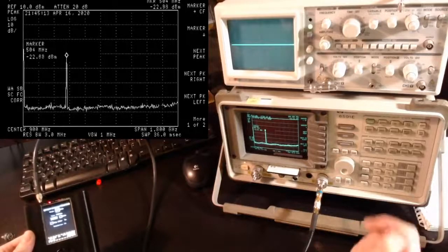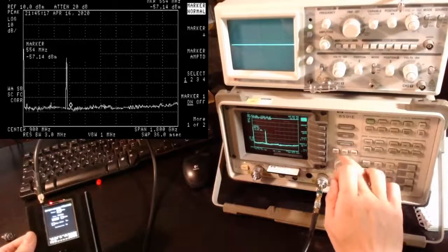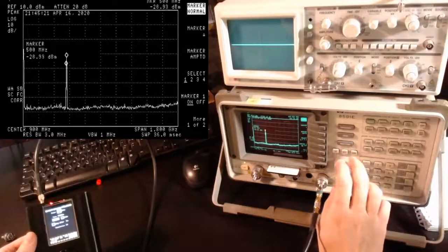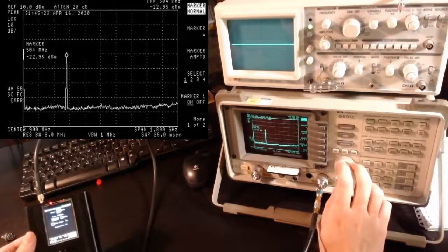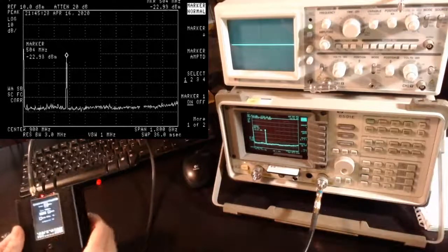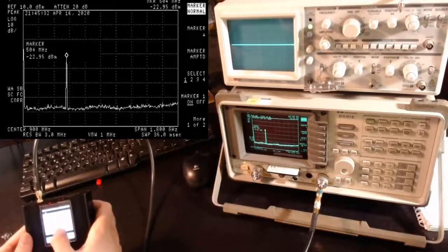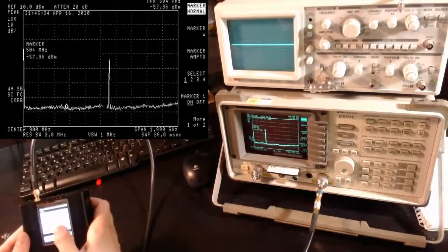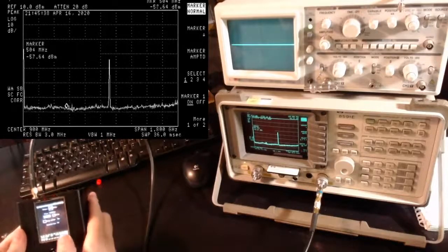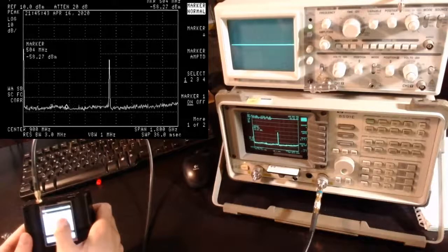And the noise floor here is, so let me just take the marker and go down, at minus 57. So it's a good 35 dB down. Okay, so the signal is pretty clean, and I think we should be happy about that. And let's see what happened at 1 gigahertz. So yeah, same thing. So it's pretty good. And let's try one last thing, 1 gigahertz 500.